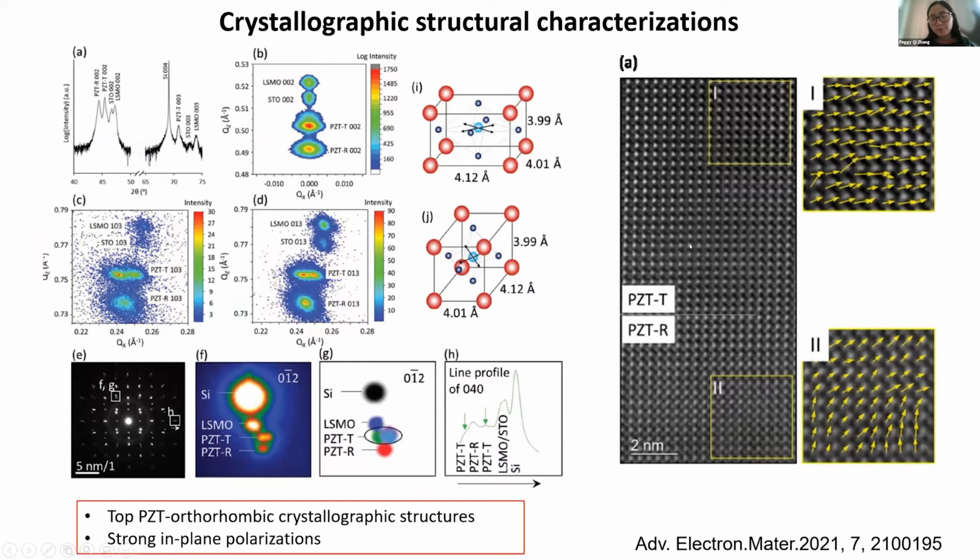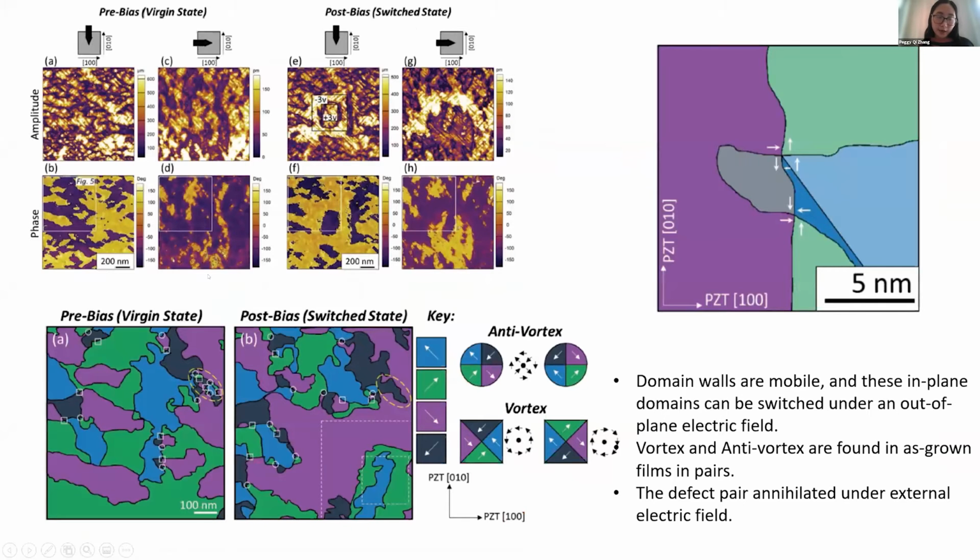According to the crystallographic structure analysis by XRD and TEM, we found it has very clear in-plane polarization, actually tilted in-plane polarization. All these in-plane polarizations have also been evidenced by piezoresponse force microscopy.